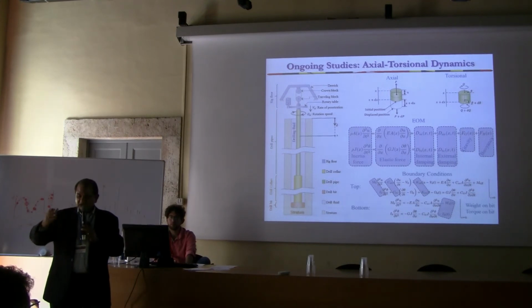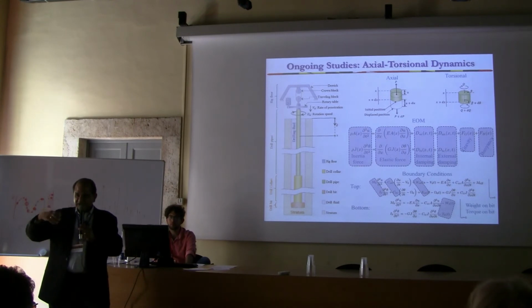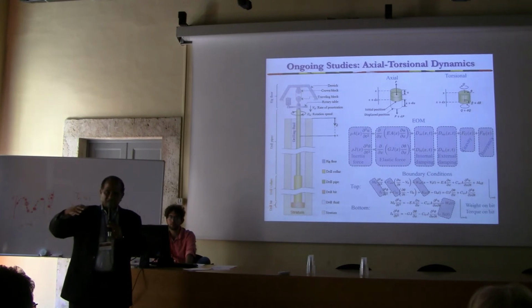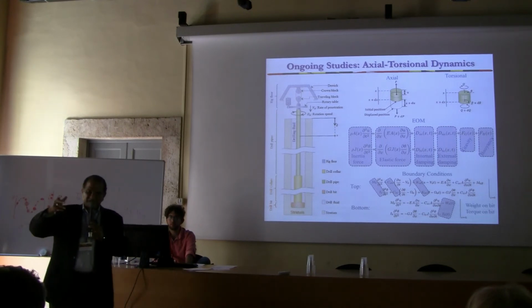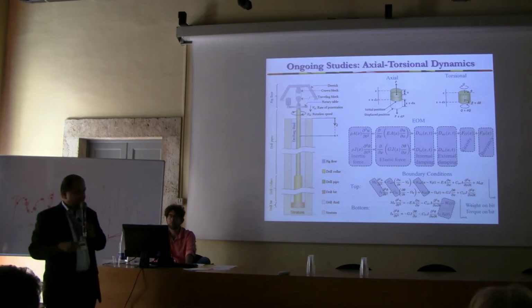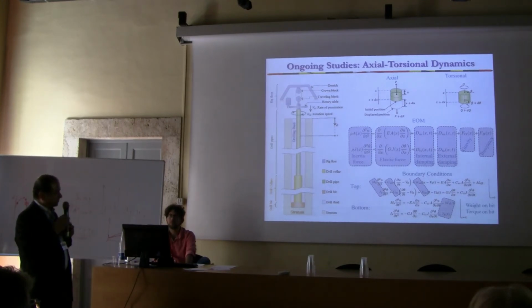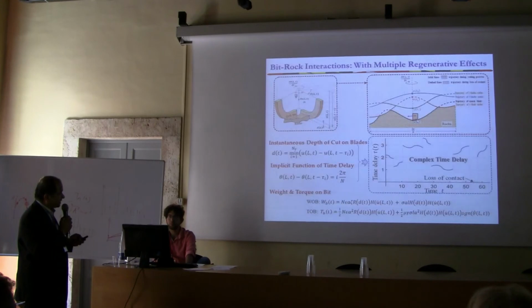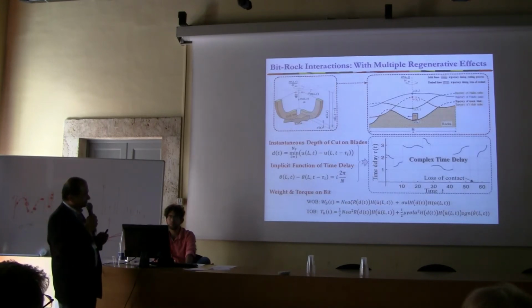You like to make the top drive very stiff, and in some cases what that means is a fixed boundary condition up at the top. In other cases, depending on the depth, you like to have a combination of stiffness, dampers and inertia to capture the top drive itself, and this model will allow you to go in that particular direction.